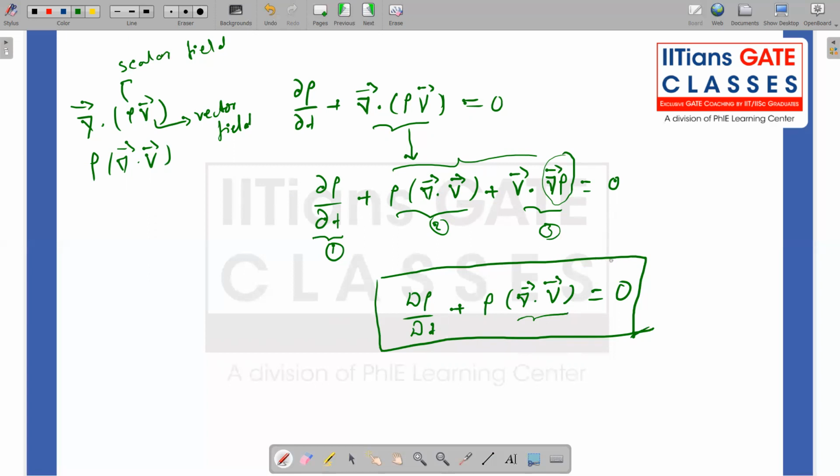But it is not necessary that if the divergence of the vector is zero, my flow field is always incompressible. It is not necessarily true, but it is a very important condition when we define potential flows, because potential flow can be defined in pure incompressible irrotational flows, as well as irrotational compressible flows.